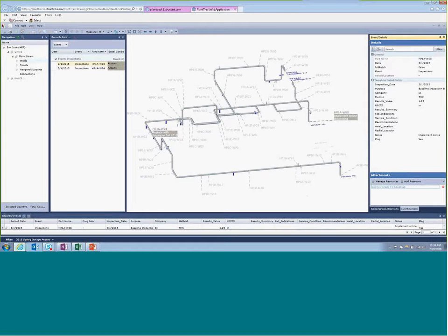As Ulrich mentioned, the third component is this online data. So the online monitoring that we do from a creep and a fatigue perspective, I'm going to focus on the creep, but the fatigue aspect is similar. It takes into account algorithms that basically use actual operating temperature, pressure, flow rates, etc. That's live, and I want to emphasize this is live. It's pulling data right now, as you're operating. It pulls this data from the historian, and Pi is a really common example. So we take this application and link it to the data historian and pull this data, and then combine this actual operating data with field-affected data.